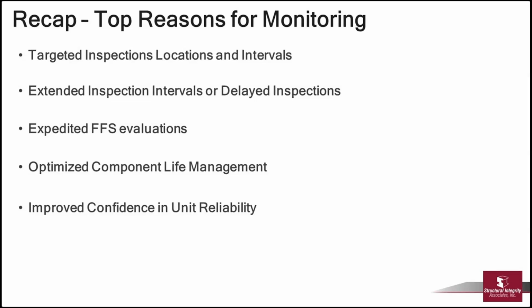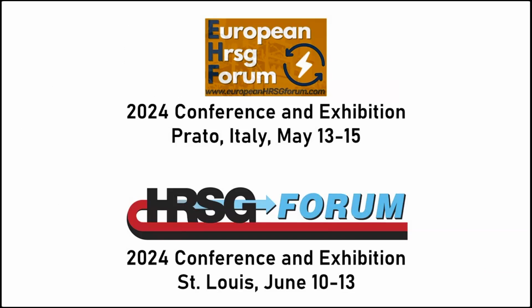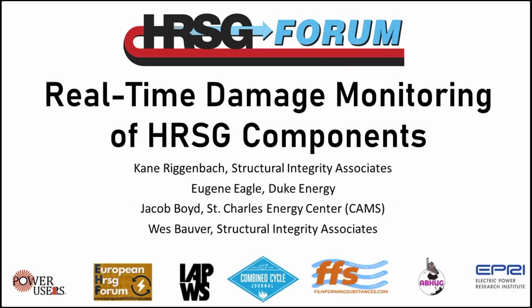I think that would be very difficult to do from specifically those incidences. Bob and I have done a lot of work with the exfoliation in HRSGs causing failure, because you can use the oxide thickness, internal oxide thickness, to estimate the temperature, and so there's a lot of work being done on that. Maybe that's one of the things that we can look at in the future.